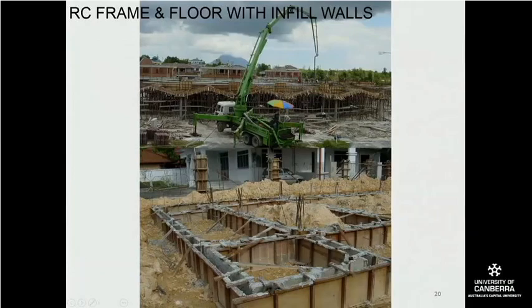You can see here how it's made. So you've got the formwork that would be cast into the ground, after which concrete would be poured into it. You can see that this formwork has been used once before because of the grey of the concrete sticking to the insides, and even for beams that are actually bent like this to give you your gable ends, you've got formwork and then you pump the concrete into that. So this is still a very common system.